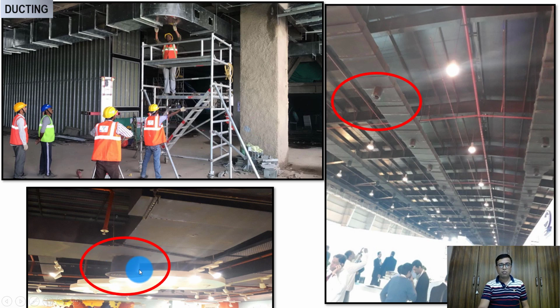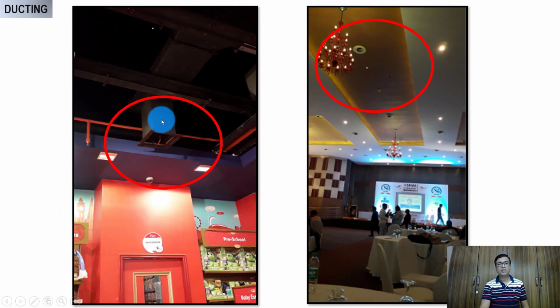Taking collar from elbows: this will not have air at any point of time. Look at this collar here. This collar is taken at the joint. The joints will be weak here. So these are some of the things which at site have to be watched, and the workman guided to do a proper job. Look at here. The air is not coming here, so they have removed the core of the diffuser. That's not the way to do it.